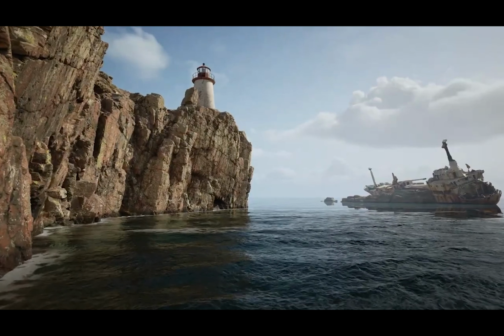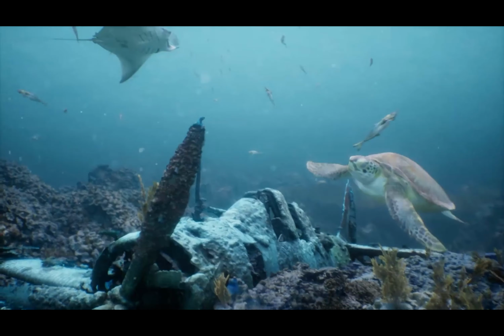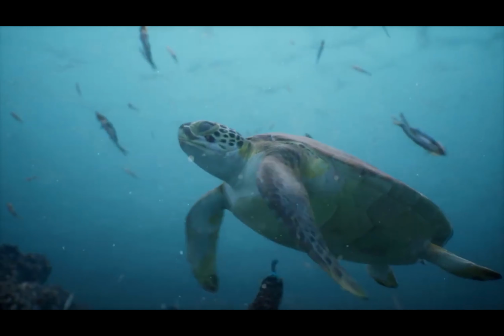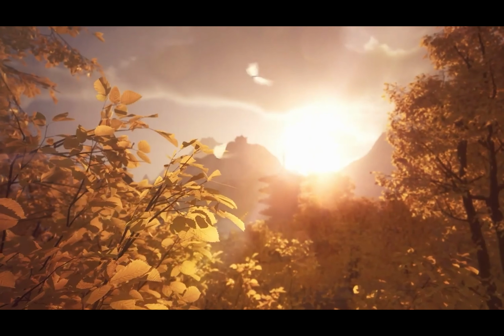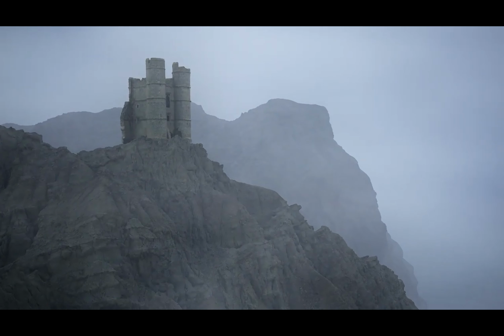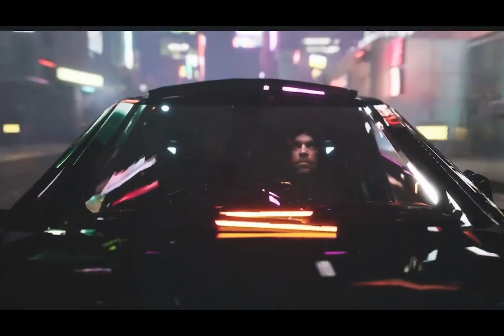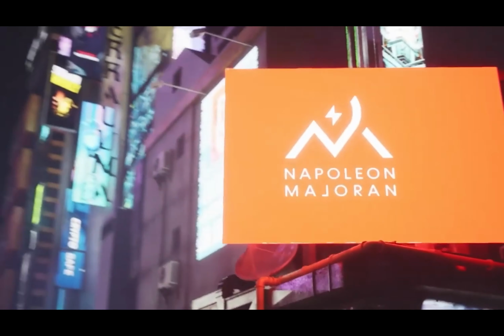Unreal Engine 5 optimizes the rendering pipeline to ensure efficient performance when using virtual shadow maps, allowing for real-time shadowing in demanding scenes. Integration with world partition. Virtual shadow maps seamlessly integrate with Unreal Engine 5's world partition feature, allowing for efficient streaming and dynamic loading of shadow data in large open worlds.